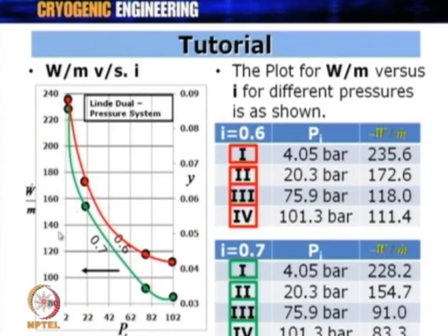Corresponding to that, the values of WC1 and WC2 change, but if you go on increasing the value of intermediate pressure, the whole mass which is getting compressed is actually in compressor number 2. So, the second compressor is now subjected to a lower pressure ratio and therefore, the value of WC2 in this case gets less and less. So, as you go on increasing the intermediate pressure ratio, the value of WC2 decreases and therefore, if you add both of them together, WC1 plus WC2, the work done per unit mass of gas compressed goes on decreasing as you go on increasing the intermediate pressure.